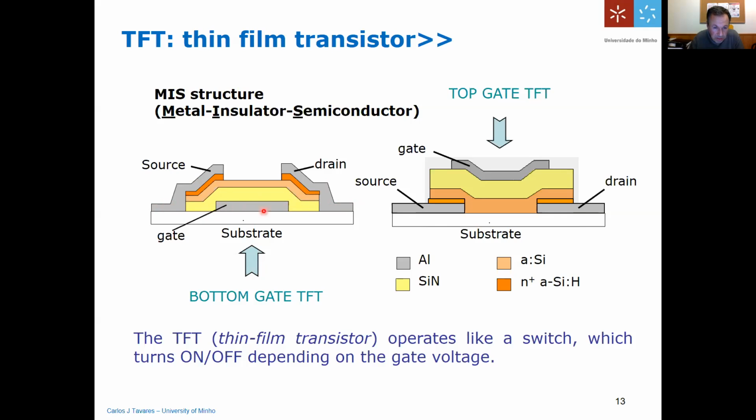Here you see yellow, but before producing this yellow material, you have to have a whole layer of metallic aluminum, which afterwards you mask, with some form of masking on the gray parts, and by chemical etching remove these parts here. Then you will have the deposition of the dielectric material, which is silicon nitride by CVD,